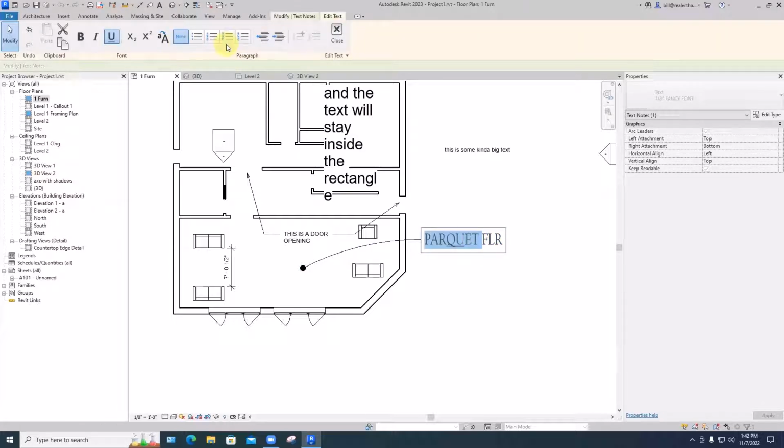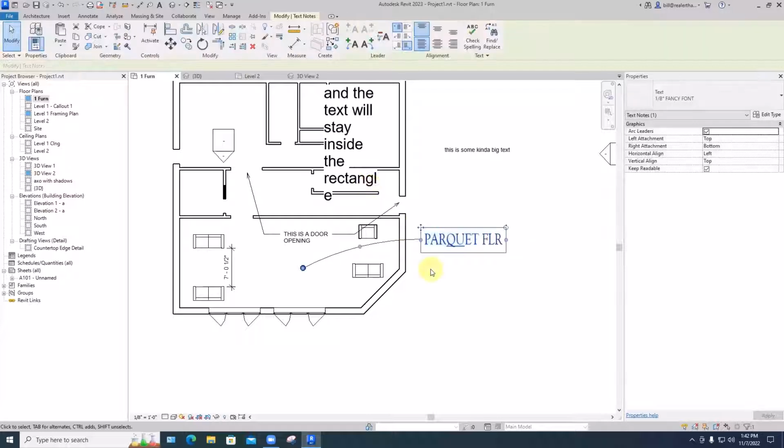You notice font and font height are not options there. One height and one font is what you get in any given piece of text. If you need a different font, create a new text type. And I guess I should say, if you have a list or longer body of text that cries out for headings in a larger font, the only way to do that is to have the headings in a separate type, which means in a separate piece of text.